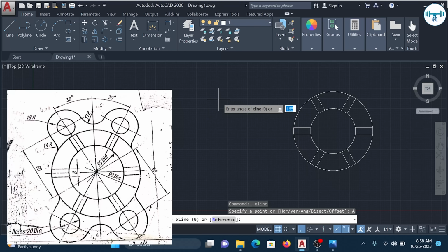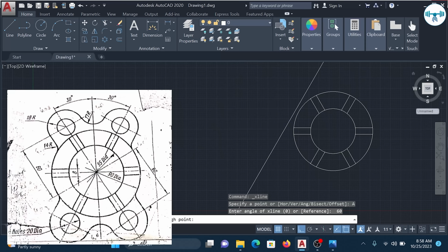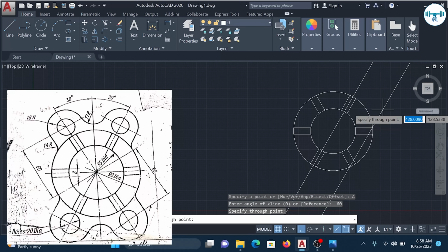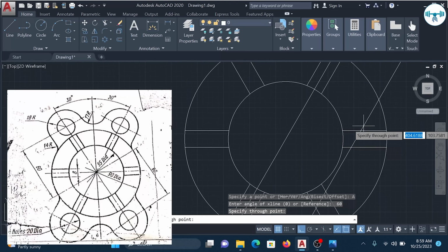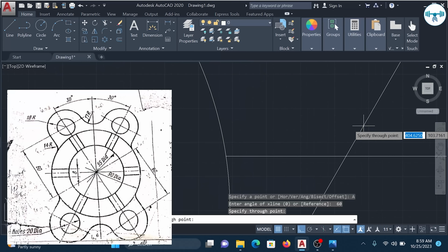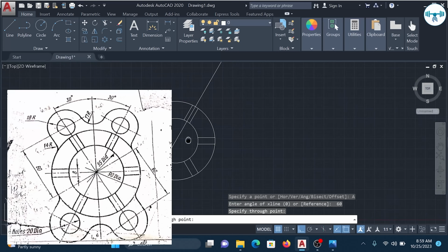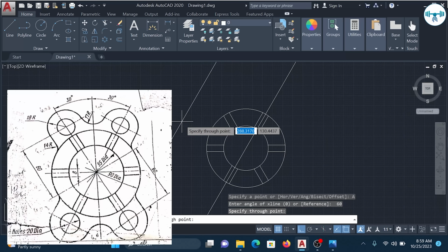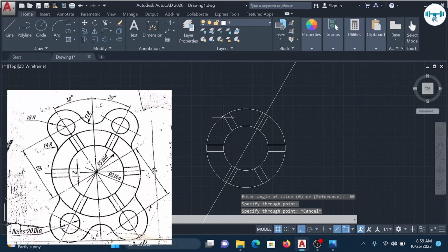So we are going to type 60, because when it makes 60 degrees with the X line, it automatically makes 30 degrees with the Y line, which is the vertical axis. So 60, enter. Can you see I have my construction line already? I'm going to move it into position. When I hover around this, the center comes out, so I'll drop it. You can see that it's very, very accurate, because it's already cutting through the center of the items that I arrayed on that axis.